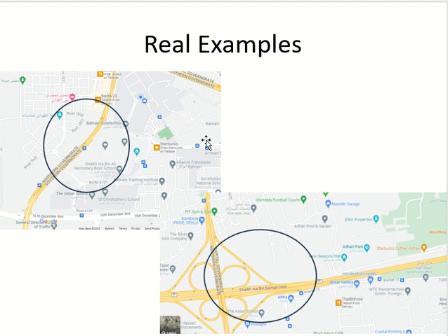Okay, on each side. If you are here, you have two options. You can go in from here, you can go in from the other side. If you go forward, then people are coming from here, and you go more forward, then again there is an off ramp. Okay, so this becomes a weaving segment. They are very close, like a few meters. From here to here, maybe it's a total of 500 meters, and you have 3-4 ramps here.